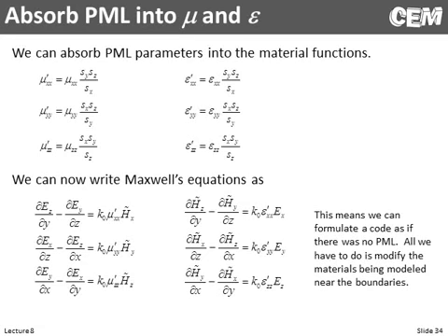One of the reasons that I like the uniaxial perfectly matched layer is that it lets me formulate, code and test an entire algorithm without considering anything about a PML. I just build in ordinary mu's and epsilons, I can test it, get it working, and then all I have to do to include a PML is, after you build the device on the grid, but right before you model it, you just modify your mu's and epsilons to build in the loss on the outside. So you add one little segment of code, and the same code that you wrote before, not considering anything about a PML, suddenly has a PML. That's really simple, and that's how I like to do it.